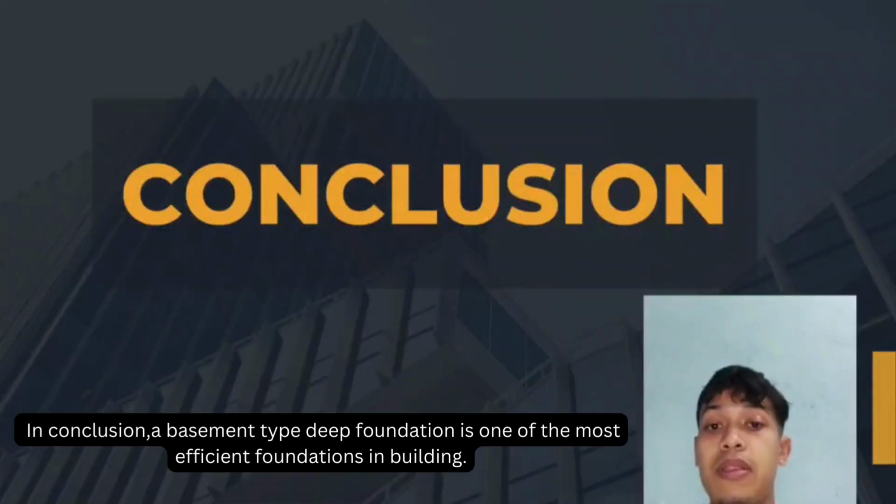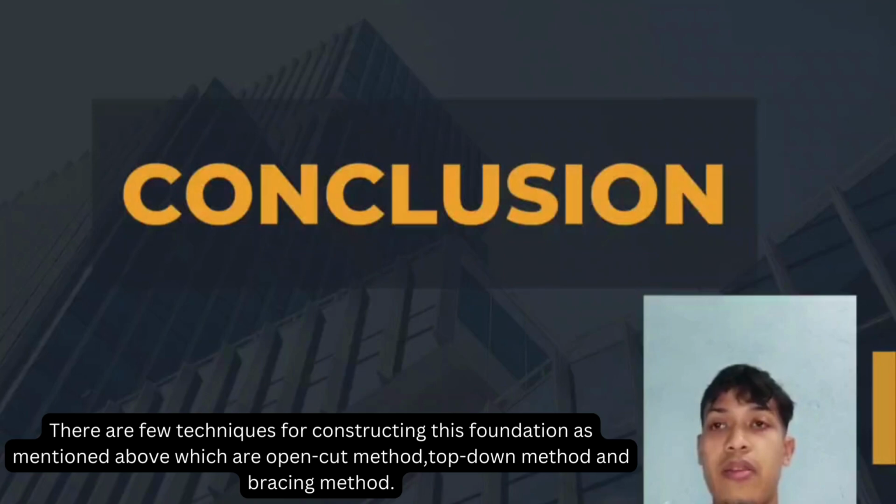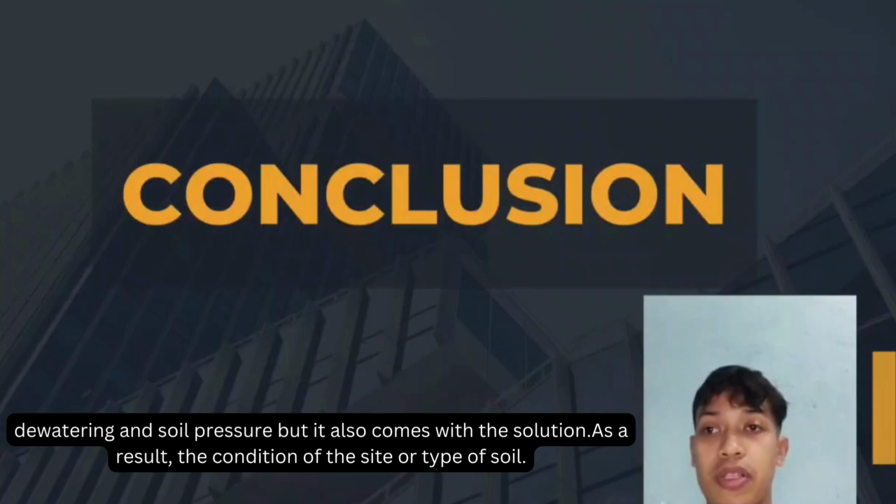In conclusion, the basement type of deep foundation is one of the most efficient foundations in building. This foundation provides storage, working space below ground level, offers protection against flood, and adds insulation and climate control. There are a few techniques for constructing the foundation as mentioned, which are the open cut method, top-down method and bracing method. And also there are a few challenges that will happen when constructing this basement, which are hydrostatic pressure, dewatering and soil pressure. But it also comes with solutions.